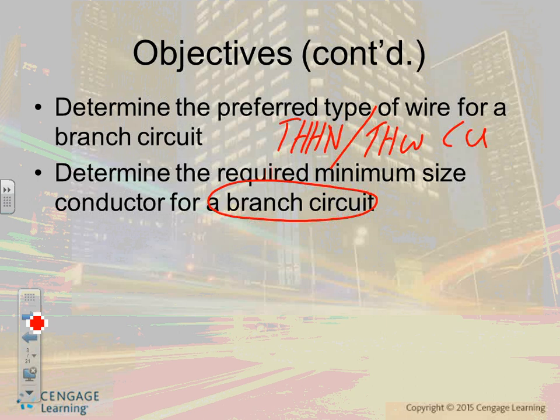Now let's switch to commercial, because we're commercial now. In commercial, do you use 15 amp circuits? Can you by code? Yes. Should you? No. Drop the 15 amp. Can you use number 14 in commercial, or should you? No. 12 is your minimum.